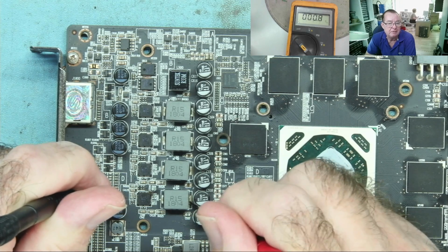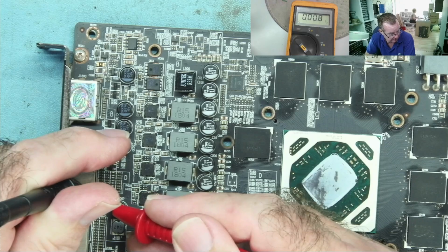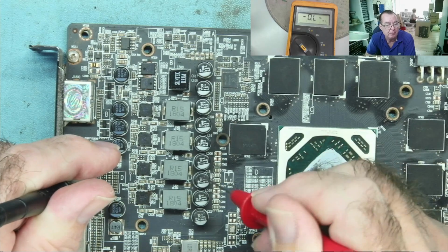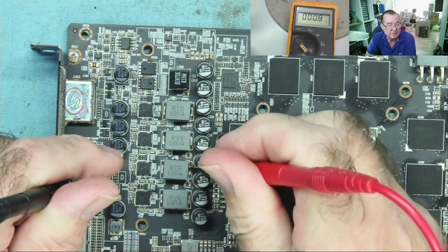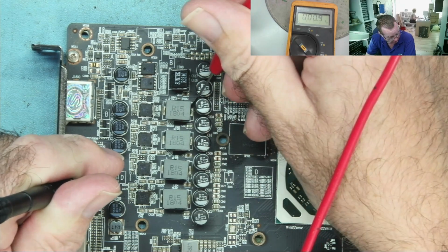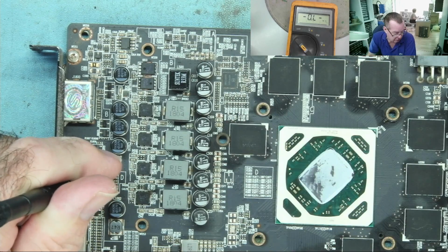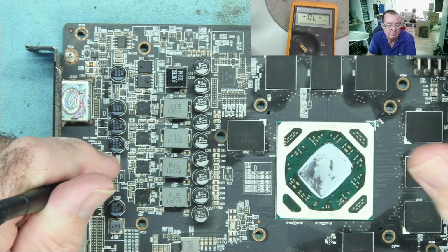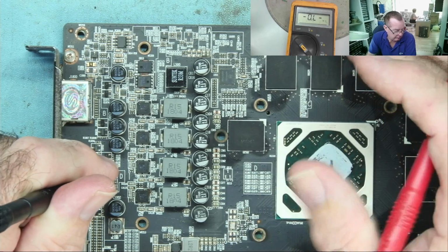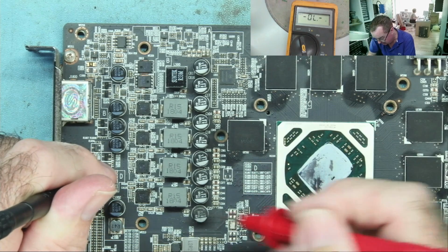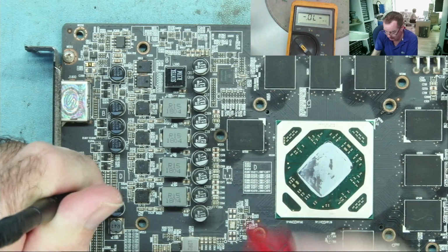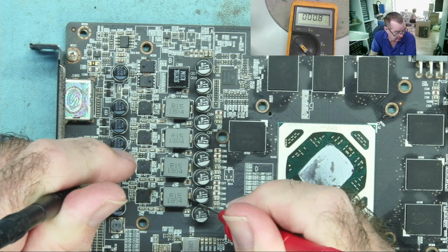It's saying 0.8 of an ohm, okay? If we short the thing together, it reads about 0.4. 0.8, 0.8, 0.8. That is not a short circuit. Modern GPUs, you can expect them to read 0.4 of an ohm, 0.3, 0.2. That's quite normal. If you read them on diode mode or continuity, they will just read like a short. Yeah, you have to use resistance range and just expect a low resistance.